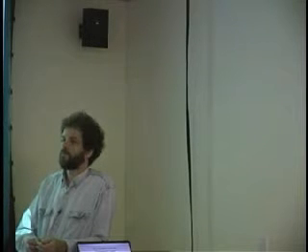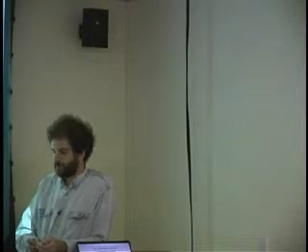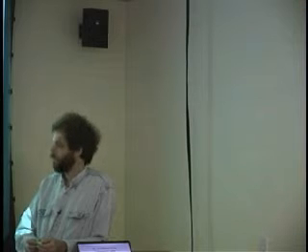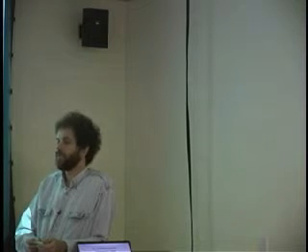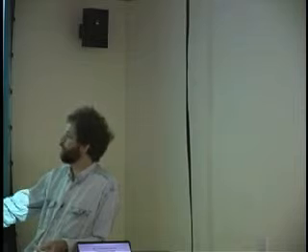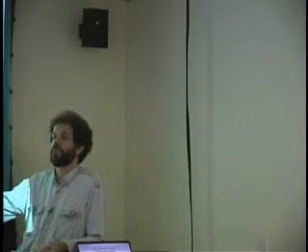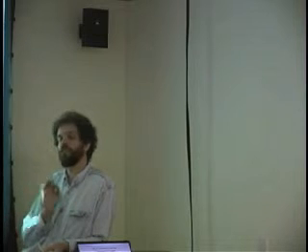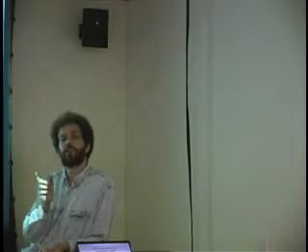Because when you set up the system, you've made extremely conservative assumptions about all of the various things we've been discussing. That's absolutely right. Now, we haven't talked yet about how you figure out how long the setup and the hold time are, but you can know that it's going to have something to do with that symbol T sub W we talked about a few slides back, which was how long do you leave in between when things change on the input to guarantee that it's hazard-free.